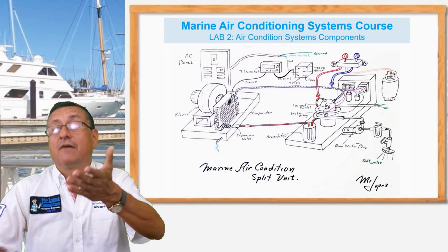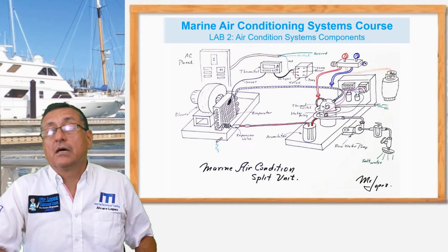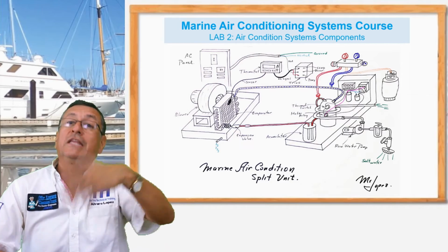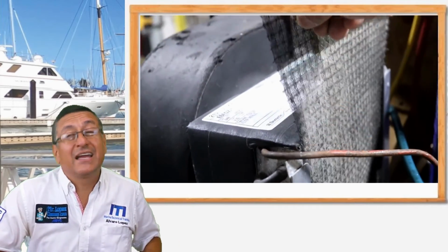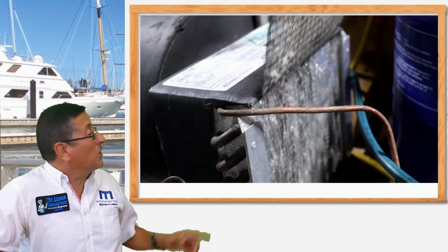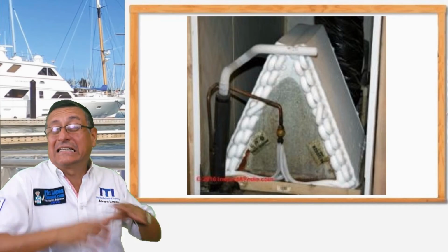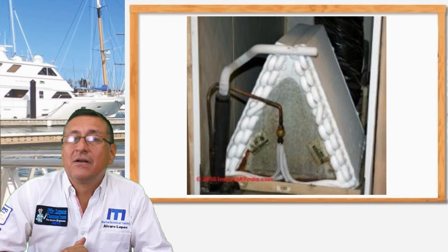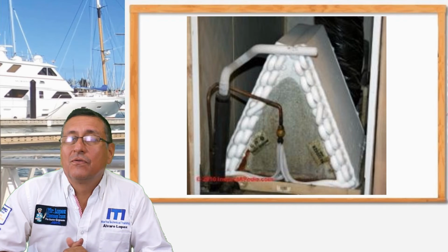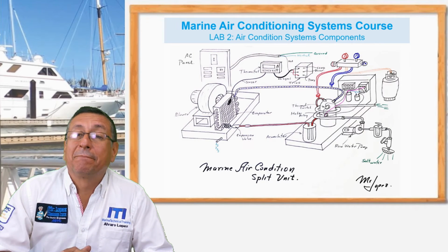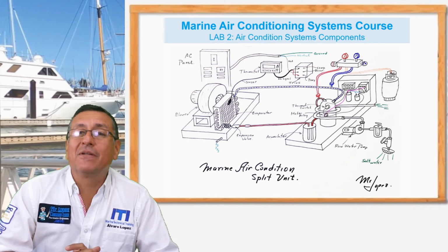You have a high temperature because the raw water circulation is not good. Or in the evaporator, you have the air filter clogged, and because the air filter is clogged, a block of ice covers the evaporator, and the system stops for bad service. You need to identify where the problem is.